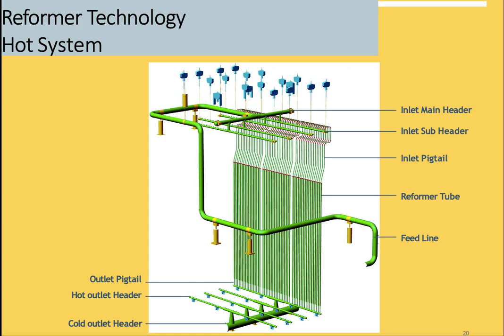High pressure drop across the reactor. I mentioned that the delta P across this tube is very, very critical. What are the symptoms for this high pressure? Increased compressor load if you are working with a compressor to supply the feed, reduced feed throughput for sure, and uneven tube temperature. The root cause can be carbon formation for this criteria, or catalyst fines, which make resistance to the flow of the fluid going through the tube, deformation, or salt deposition inside the tube itself.